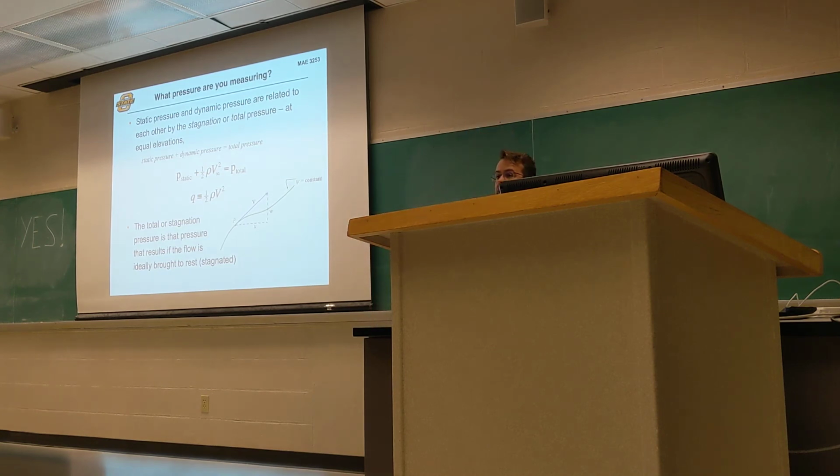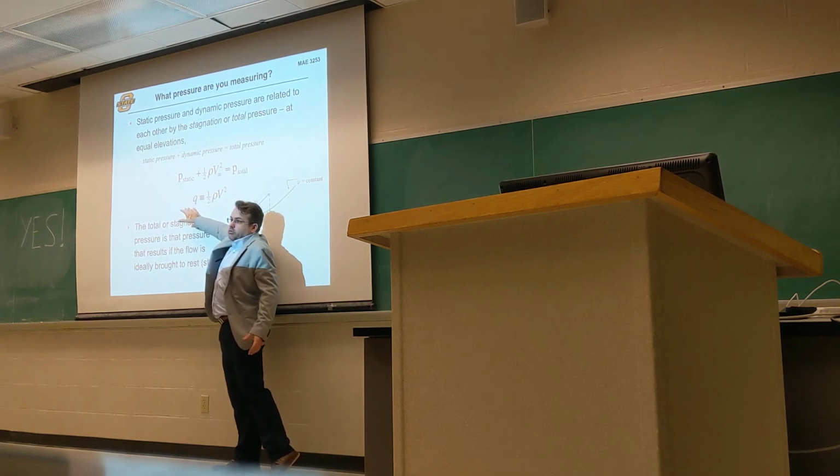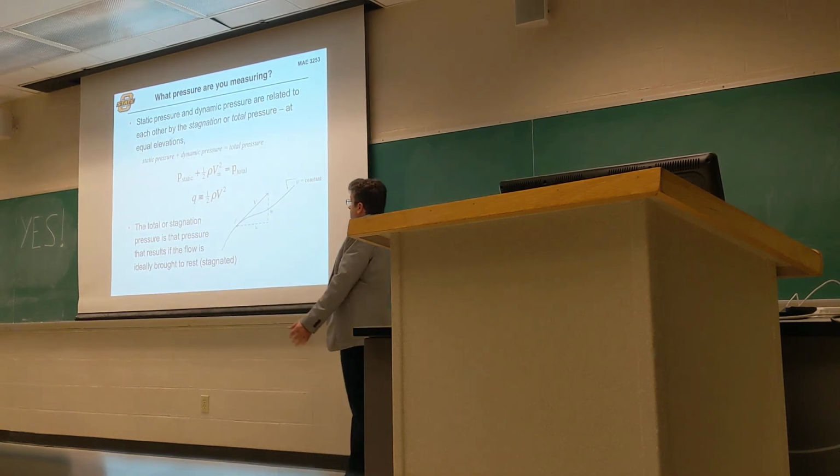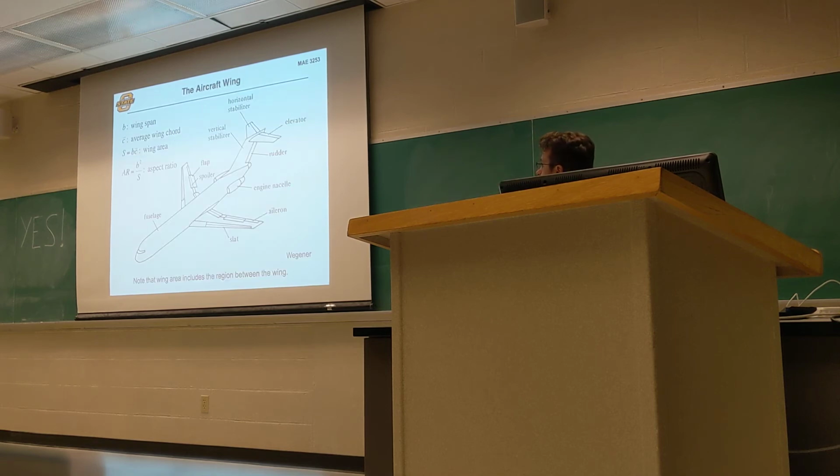If you're looking at the aerodynamic loads on your rocket and your airframe, your fairing, that's what you're designing for with this piece right here, because those are the forces actually acting on the rocket. Now, we can utilize this in lots of different ways. We'll come back and talk about this for measuring airspeed. And so our basic pitot probe operation just goes back to this simple equation right here.